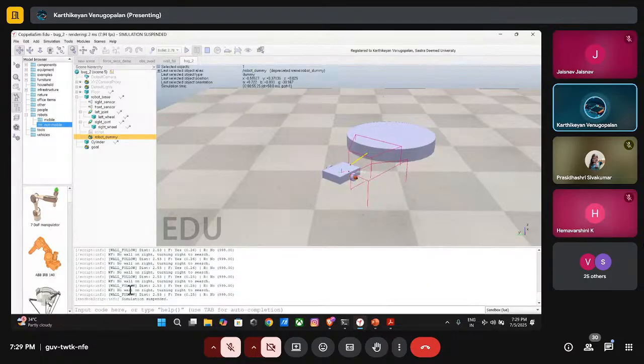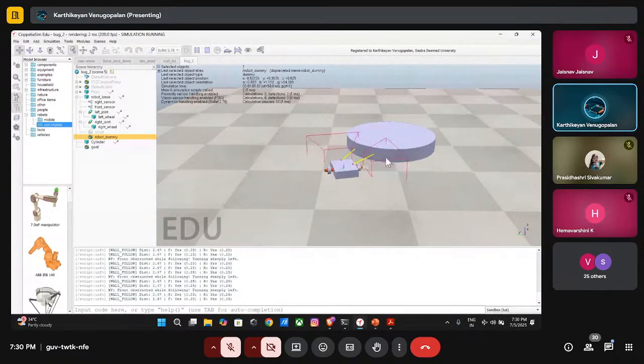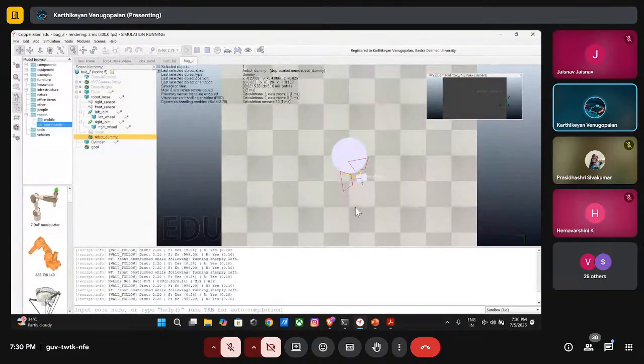We had a hit point here, and there is no wall on the right side. So what we have to do is turn right to check whether there is a wall. I am turning right, yes, a wall is detected, and the mode is changed to the wall follow state. Now we follow the wall, similar to right wall following.